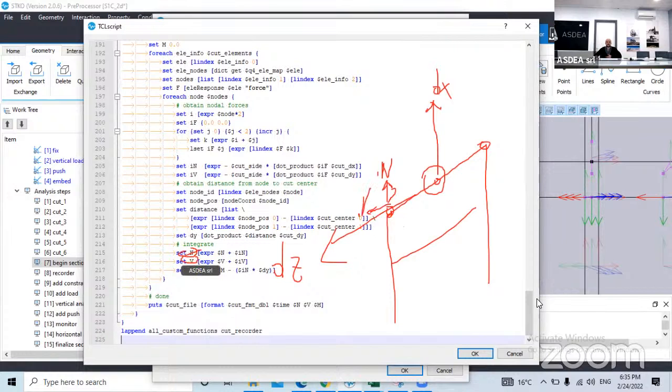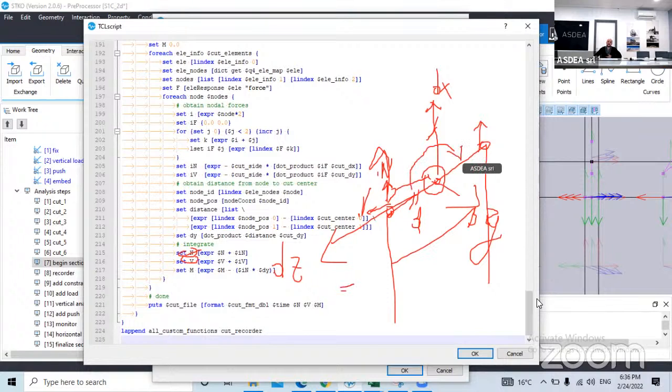But then there is an extra component because the n times the distance from the center can produce a bending moment about the z-axis, okay, which is this one. So sorry, the y-axis in the local direction of the beam. The minus, because if I have a n here, okay, sorry, a positive n, which is pointing aligned with the dx, in a positive distance, which is this one, along the dz, it will produce a negative bending moment because the bending moment will point in the opposite direction of minus c. That's why I need to put minus here instead of plus. So is it clear?